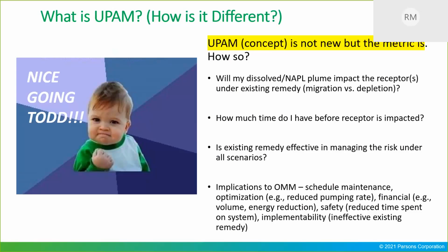Perhaps when you have low groundwater level conditions, maybe the perceived risk is significantly lower. So that's when you may want to do some maintenance work. You're able to optimize your remedy because, depending on the scenarios, you don't need to pump as aggressively as you need to be, which ties into the next aspect, which is the financial metric, the tangible and the intangible cost